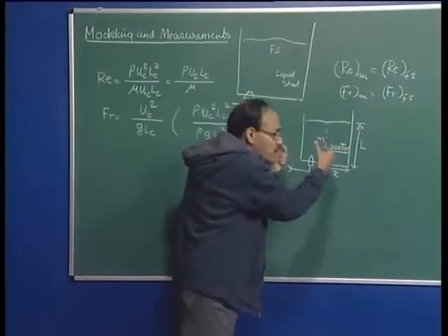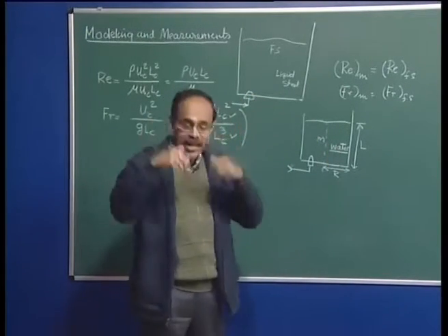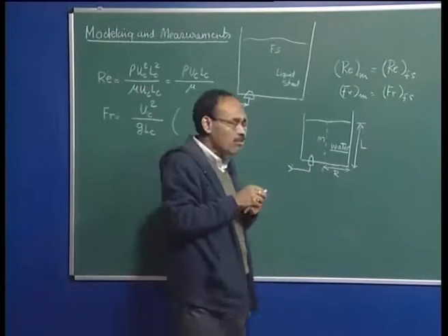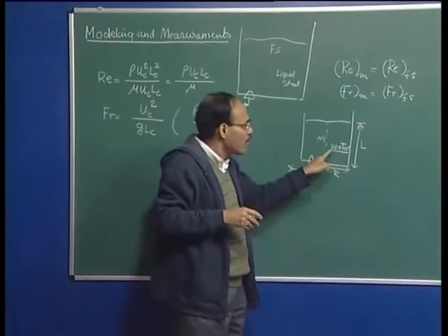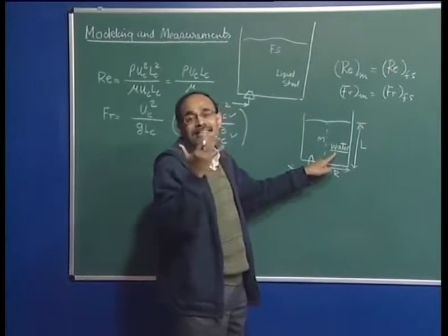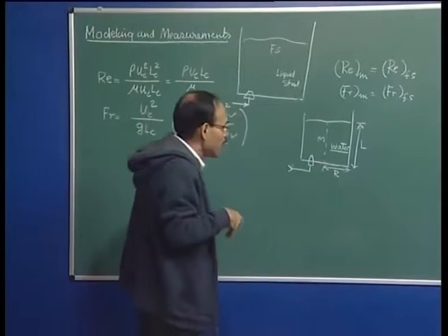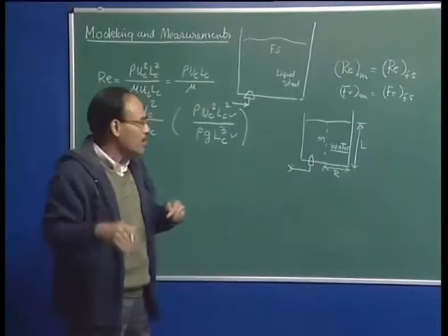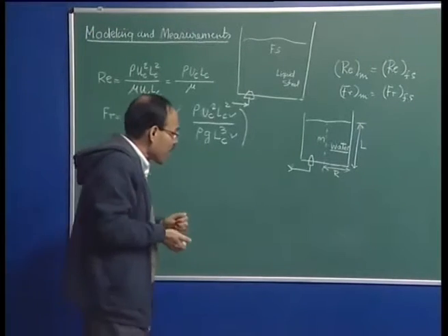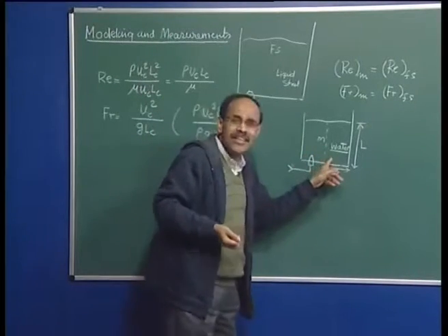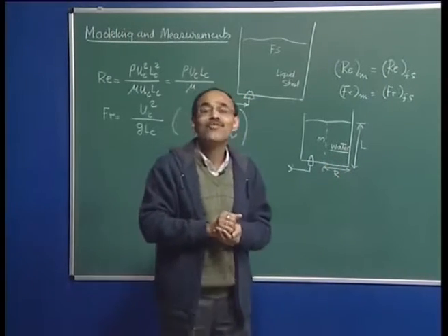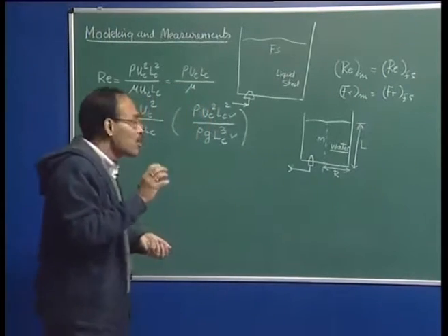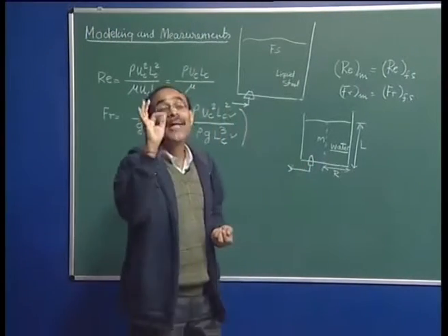So, when I construct a physical model, I am examining the possibility of physical visualization of the flow, and therefore, if I use water, I can visualize the flow very nicely if the entire ladle is fabricated out of plexiglass or transparent plastic sheets. On the other hand, if you say, sir, I want to use mercury, in that case I would say that physical visualization of the flow is not possible because mercury is not transparent. So, using water gives us many advantages.